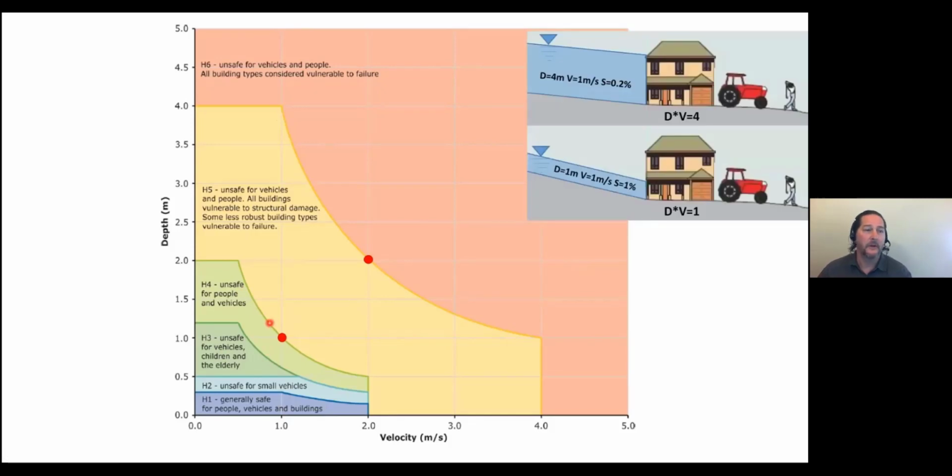Now, one thing I wanted to highlight, again, for an upcoming webinar we've got, in trying to protect riverbanks and things from the damages resulting from flood waves, is the depth times velocity plot. And this is actually a question that Marty Jacobs, looks like, on the chat line has asked. He says, most hazard assessments refer to the DV product as the prime indicator. I suggest this is a historical artifact, and a better parameter would be shear stress, also a function of D times V, which is implicit in the hydraulic calculations and might provide better linearity. And this is something you can tune in on our webinar coming up in about 2 months' time on shear and riprap protection.